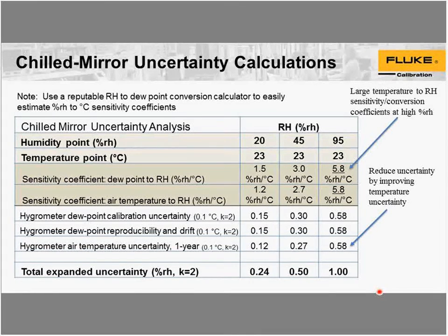It's slower, but it works well for its design application of being in a room. So it provides really good repeatability, but it's just slow to respond to changes in humidity. Whereas with the capacitive sensors, I'm impressed with how quickly they respond to a change in humidity.